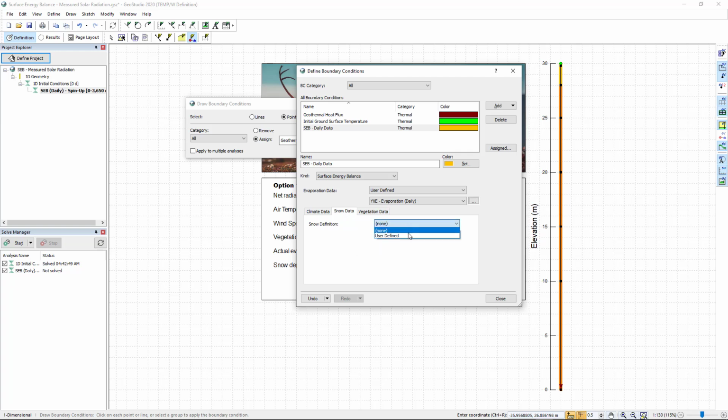Move over to the snow, user defined, snow in this case. So I'm going to define the thermal conductivity first of all. So thermal conductivity of our snow is set equal to, just a sec here so that I can find the value. Yeah, there we go. 1.20949 to the power minus 4 kilojoules per second per meter per degree Celsius.